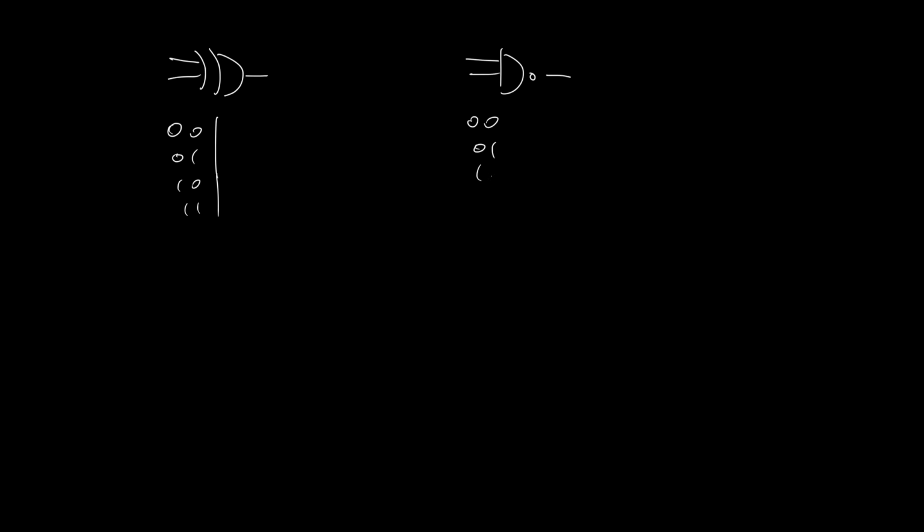While there might be simpler techniques for solving this particular problem, we are going to look at a general technique, and the starting point is to take our truth table and write it in a canonical form called sum of products form. This will work for any truth table, not just a 2-input truth table, but even a 10-input truth table or a 100-input truth table, although of course you'd run out of time doing that by hand.